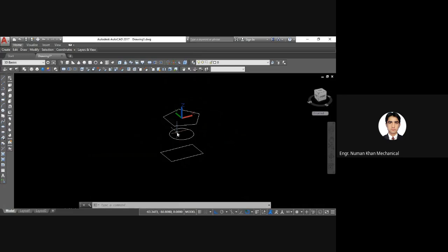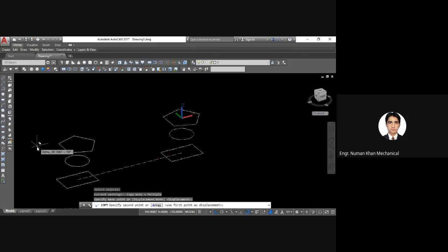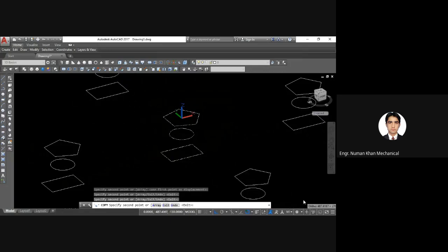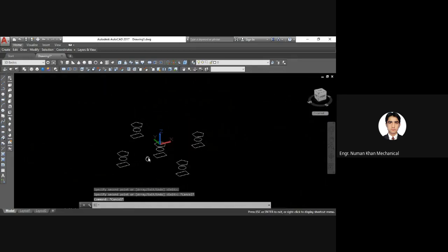So for this we will use the loft command, where we join the different cross sections in lofting order. It is asking me to select cross sections in lofting order, and you should keep in mind that this lofting order is very important in selecting the objects. I will show you the difference. Before this, let me take a few copies of this object to see the difference among different options. Let's do the middle one first, then we will talk about the others as well.